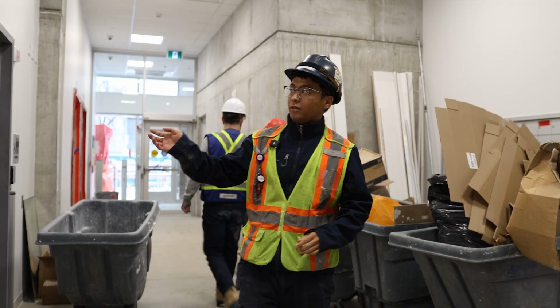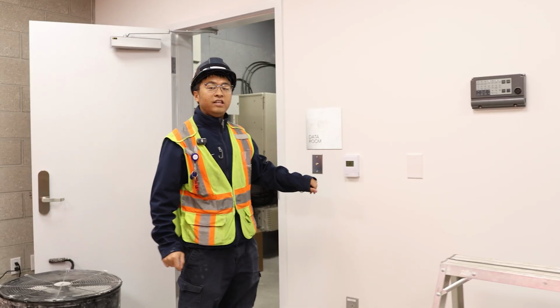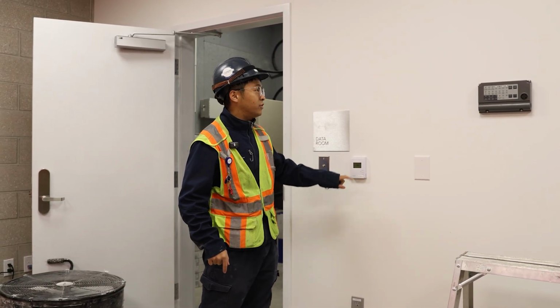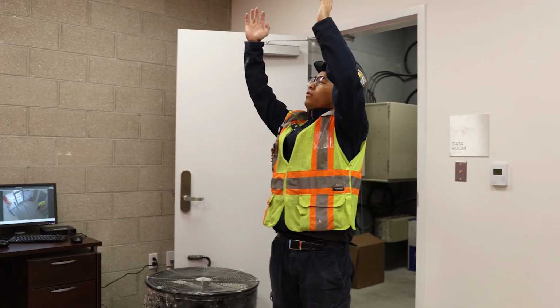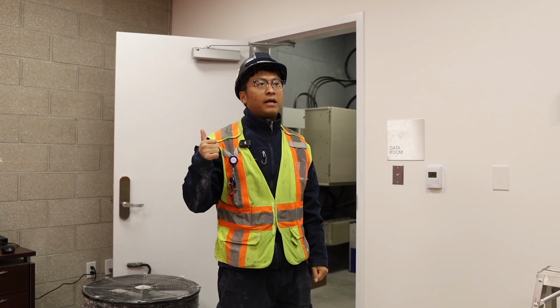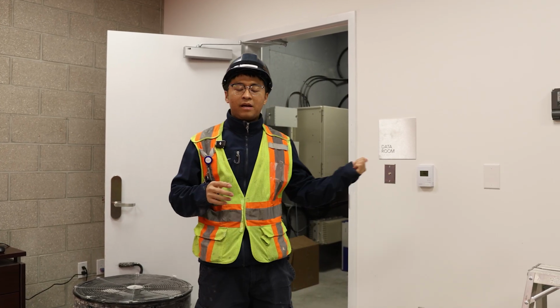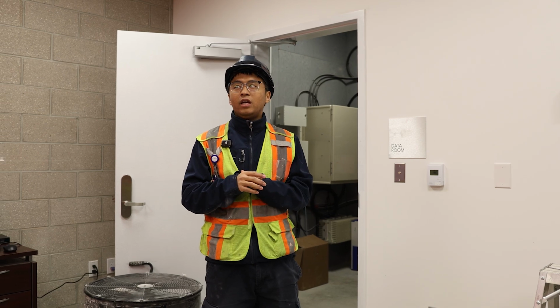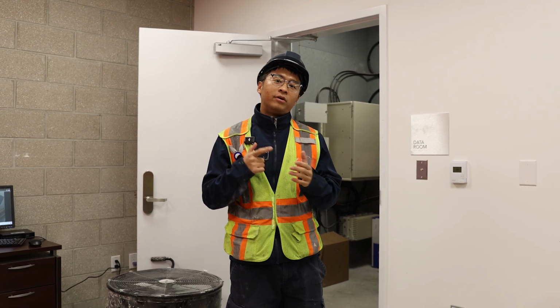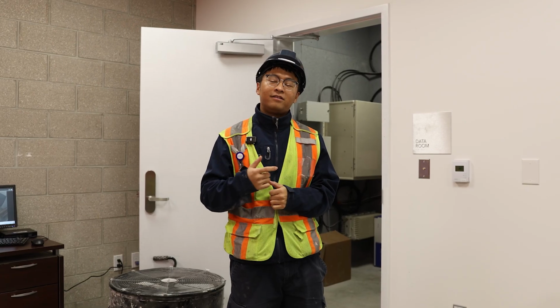If you step into the office, we have a DDC fan coil unit. This is fan coil unit number 5. This is our space temperature, and the fan coil unit will be right here above the ceiling. The BMS controls the space temperature, and we control the heating valve, cooling valve, and the fan enable. We also monitor the fan status and the supply air temperature.